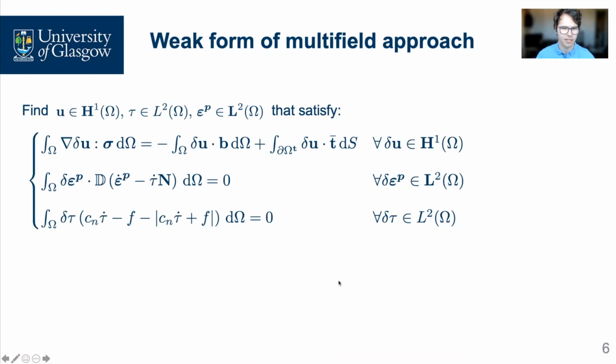So the weak form for our finite element is derived by the standard Galerkin approach, resulting in the following set of discretized equations. To approximate the primary variables, which in this case will be the displacements, plastic multiplier, and plastic strains, we will use the hierarchical shape functions provided by MoFEM.